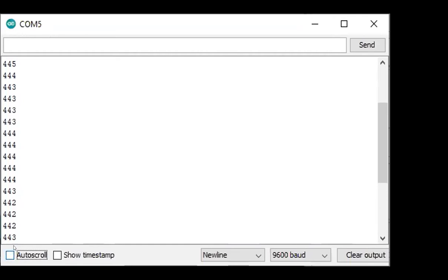And this is, as we mentioned previously, something called floating. This is the same sort of reason that we use pull up and pull down resistors, right? When there's nothing connected to the pin, there's no positive signal, it's sort of randomly charging and discharging the small capacitance. You're going to get an unpredictable number depending on the ambient electrical conditions and trace layout on the board.